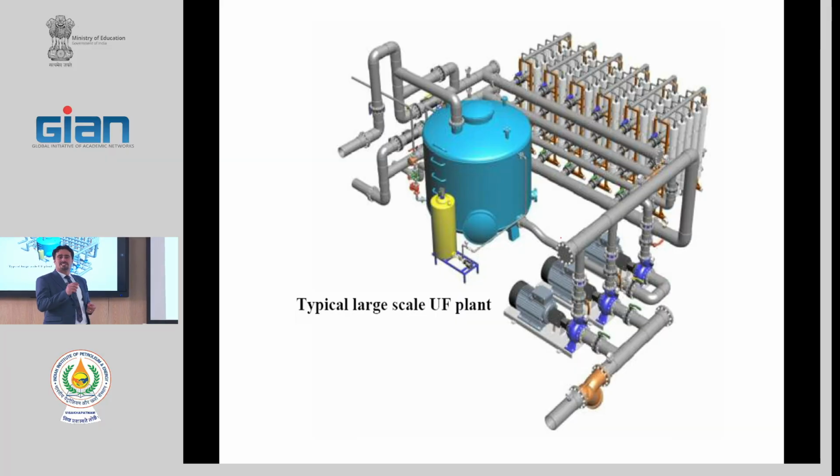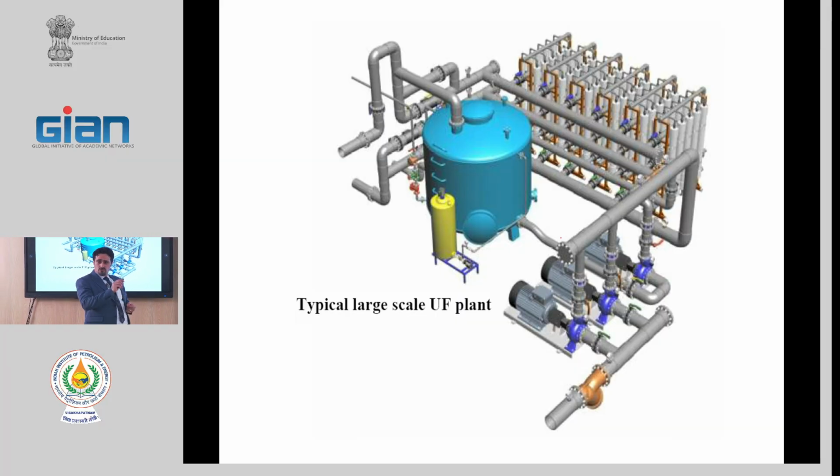Mostly it is pH adjustment. If we control the pH, we can reduce the fouling. We can change the protein charge, membrane charge, or we can change the sedimentation of the salts on the RO. Or we can use anti-scalant.